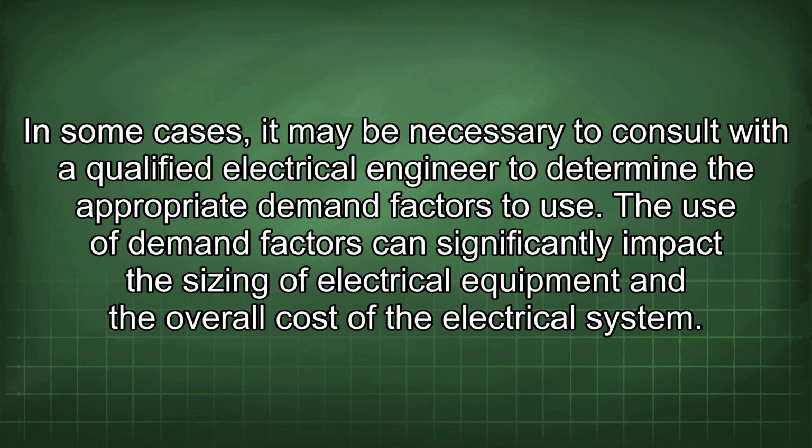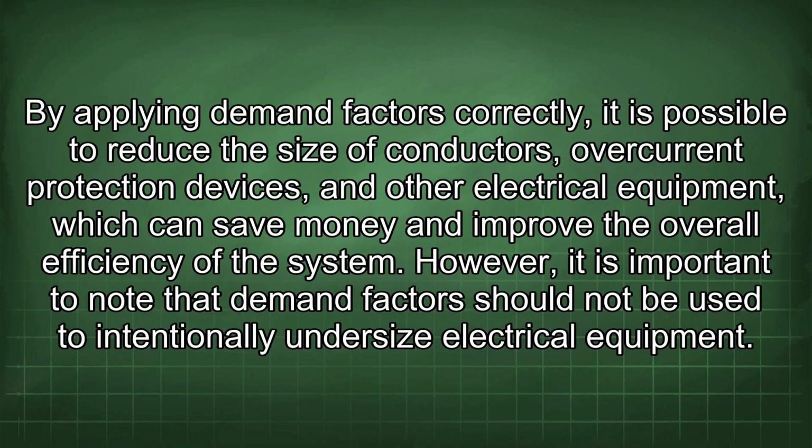In some cases, it may be necessary to consult with a qualified electrical engineer to determine the appropriate demand factors to use. The use of demand factors can significantly impact the sizing of electrical equipment and the overall cost of the electrical system. By applying demand factors correctly, it is possible to reduce the size of conductors, overcurrent protection devices, and other electrical equipment, which can save money and improve the overall efficiency of the system.